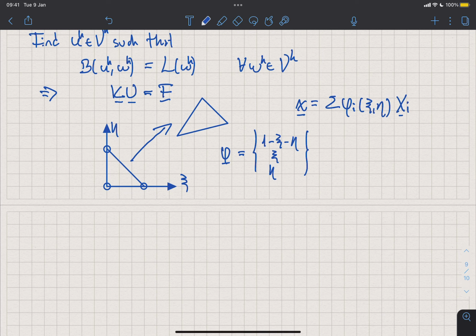That is the way we do it. In this context, these are coordinates, and this guy here is going to turn into a matrix, because you have to approximate the x component, and then you have to approximate the y component. But in any case, this whole thing is approximated in the same way as the field is approximated, and therefore you have an isoparametric formulation.